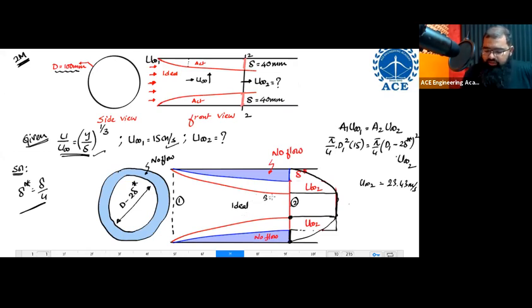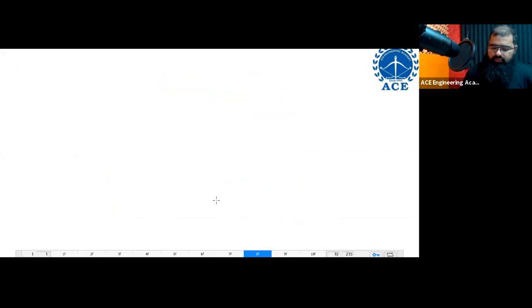Just imagine this slide itself is representing the concept of development of flow. These two boundary layers will meet at some particular point. They will converge over here sometime later on. So during the development of flow, how the velocity keeps on changing, you can understand from here only. Apart from the continuity equation, there is no other way you can solve it. Actually, look over here now. We have spent a lot of time on this displacement thickness. There are two more thicknesses I have to talk about. The next thickness we have to talk about over here is known as momentum thickness.